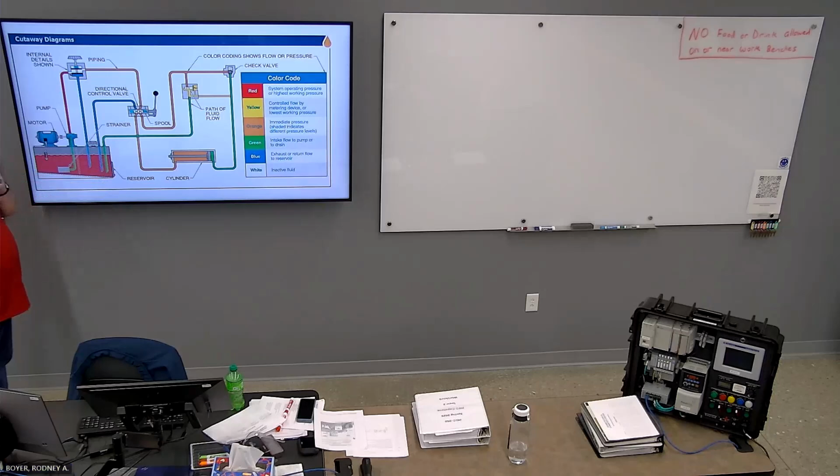So you empty out the tank, open up the little plug there, let the oil out, and then take the cover off the tank. So you reach up in there and wipe out all the sludge and the gunk and whatever's in there.